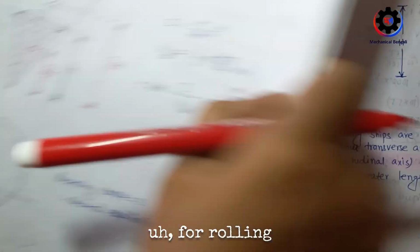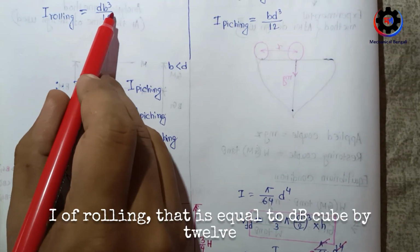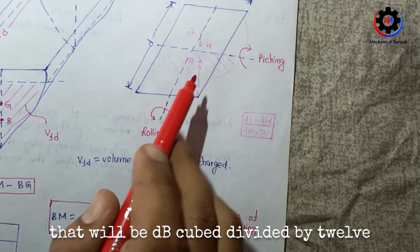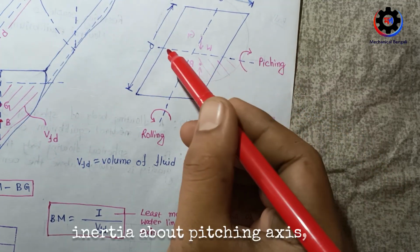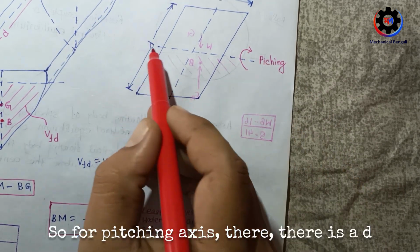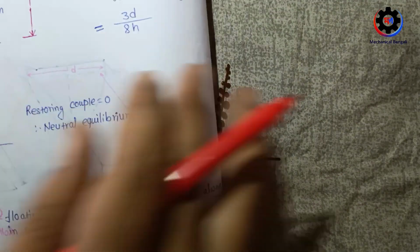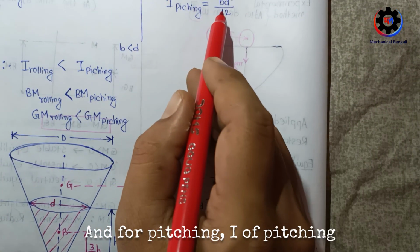Now if you want to calculate for the rolling case, I of rolling is equal to d b cube by 12. So the moment of inertia about the rolling axis will be d b cube divided by 12. And if you want to calculate the moment of inertia about the pitching axis, it will be b d cube by 12. For the pitching axis there is a d, so this will be d cube, so b d cube divided by 12. For rolling, that is d b cube divided by 12. So I of rolling is d b cube by 12, and I of pitching is b d cube by 12.